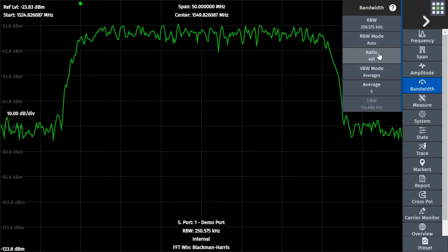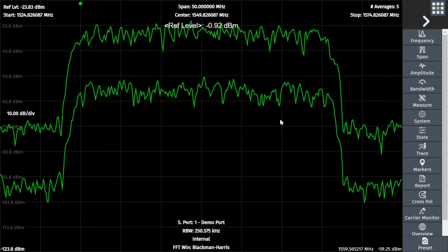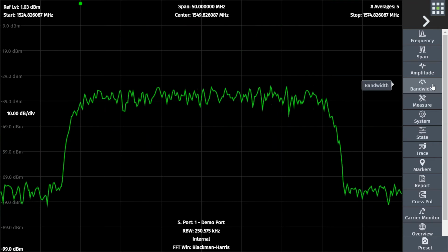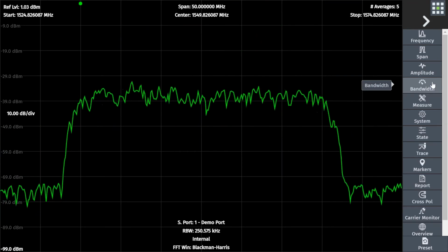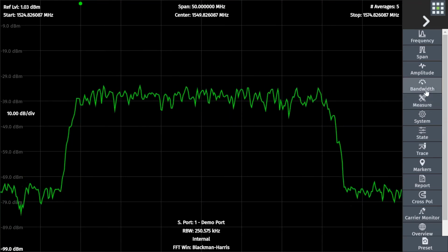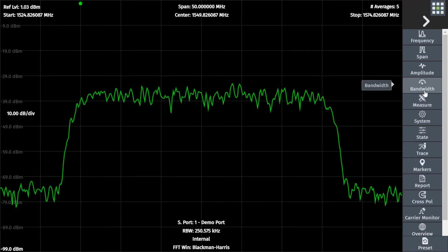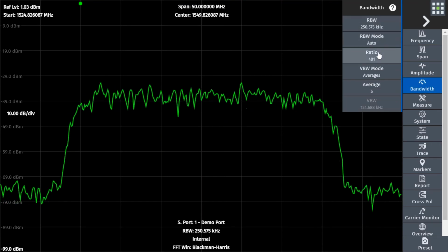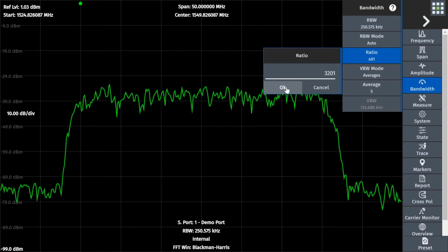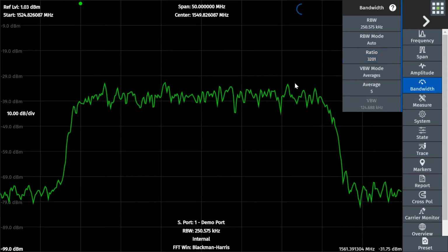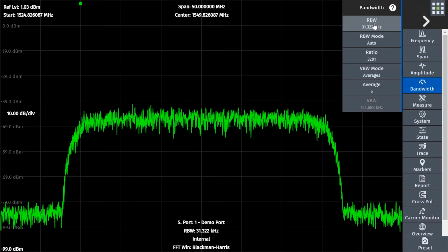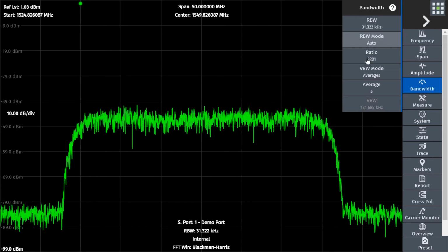Yeah, and then we can start looking at some of the resolution. So you can see here the signal looks good for a quick glance, but sometimes you want a more average signal, more smooth signal. Looks less jaggedy, but of course it takes a little bit longer to measure. So it's always a trade-off in terms of speed and accuracy. So the full controls are available to you, but if you want to do a finer resolution bandwidth, that can be done sort of in a traditional way with the res bandwidth ratio like the D3 used, or else you can set an explicit RBW as well.